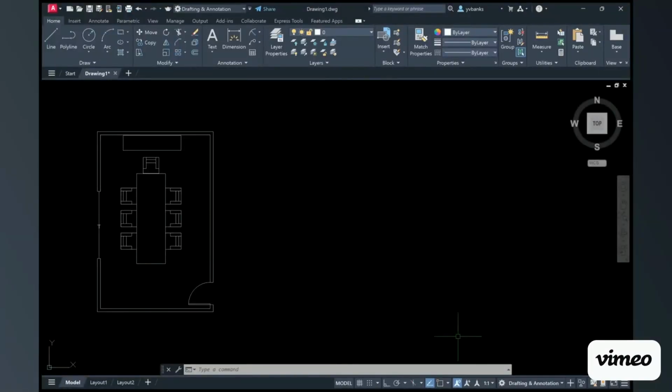For this video tutorial, I will be demonstrating how to create this small sample conference room. You're going to see multiple commands such as inline, rotate, mirror, move, and even creating and pulling in those dynamic blocks. For starters, we're going to go ahead and draft the shell of the space by typing in ML